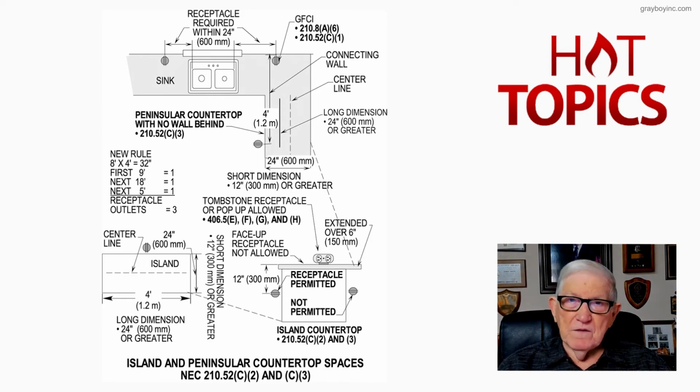So that's quite different. Now some of the electricians are saying, hey, we're having trouble getting those in that area where you have drawers, areas like that that open up, and you store stuff. It's becoming a real problem there. So we need to get with the builder if you're the electrician and say, hey, how's this island peninsula going to be constructed? Because I've got to have room to get the number of receptacles based upon the dimensions